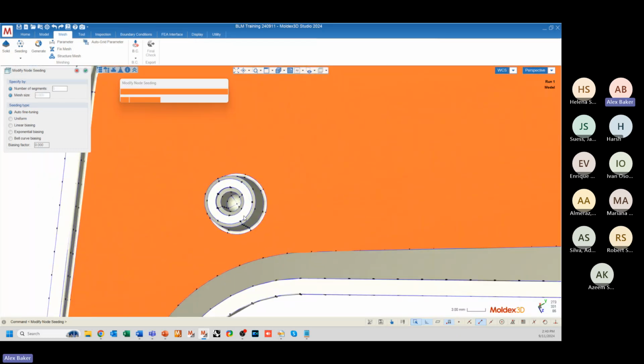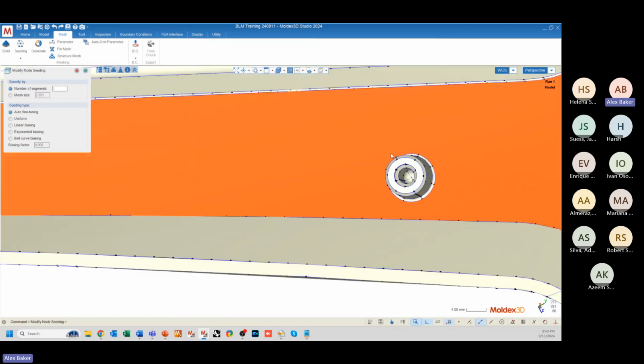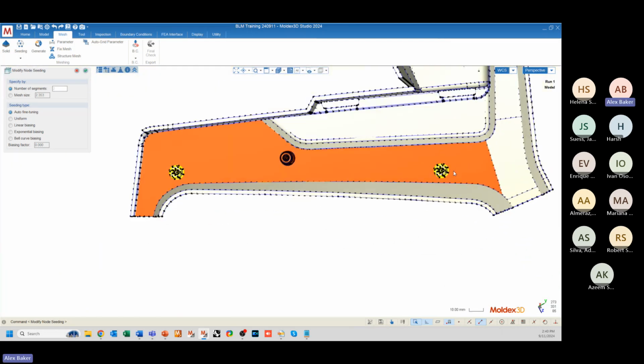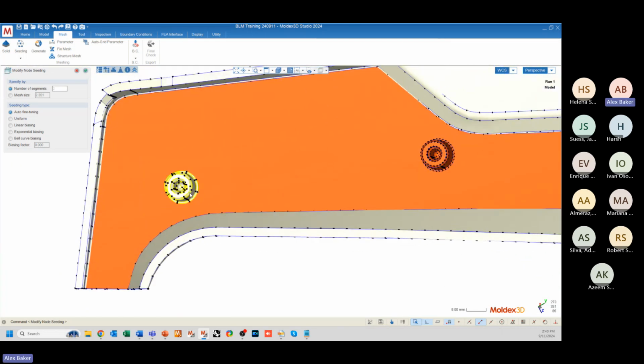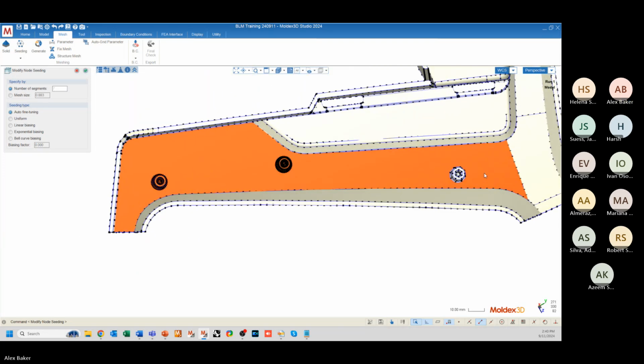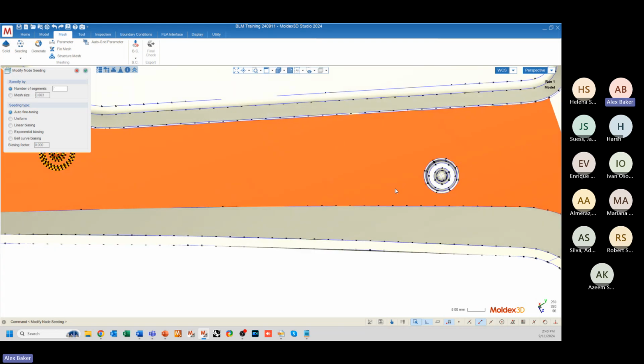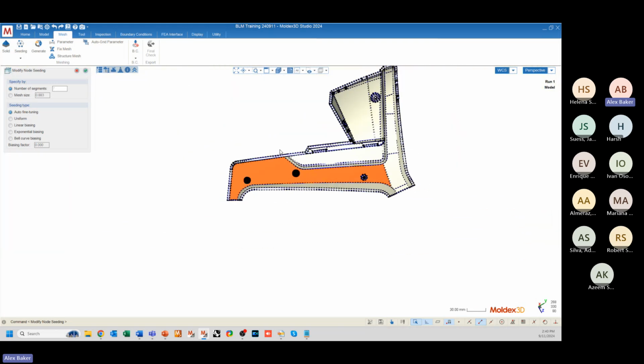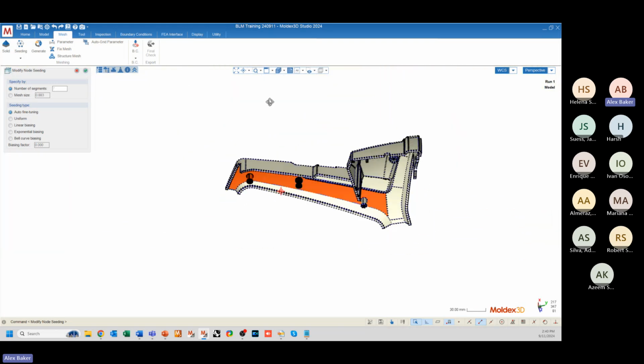All right, and you can do this for as many feature lines as you want. You can hold the Shift button on your keyboard to multi-select feature lines you want to select manually. I'm just going to do this one over here. Mesh size, and we'll do a mesh size of 1. So that automatically goes to 0.885, which should be very similar to this one, which is 0.883. All right, I'm going to leave this one as is just so I can contrast when we actually create the surface mesh what those end up looking like.